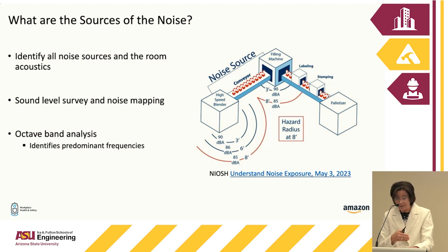And many machine noise measurement standards, and they're not mandatory, they're standards, especially for those for machine tools, specify that noise is measured with the machine idling or running unloaded at maximum speed. Again, this means that the sound levels measured are not characteristic of what's going to happen in a work environment.